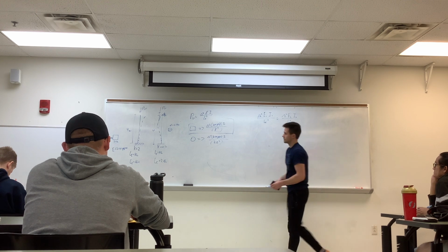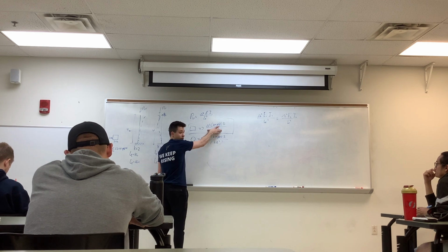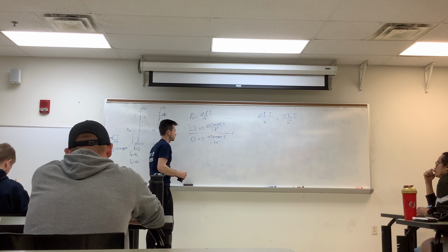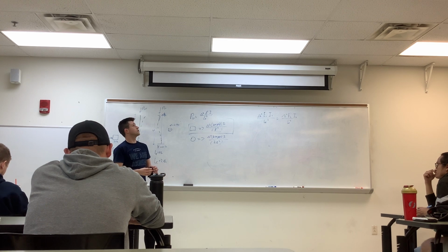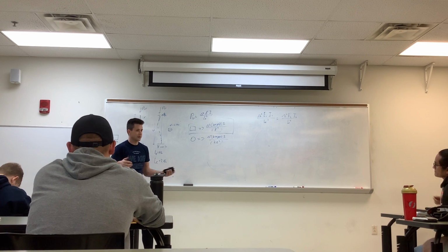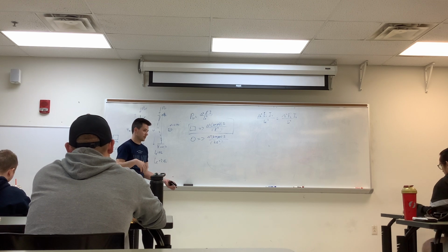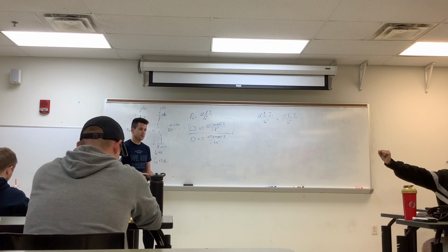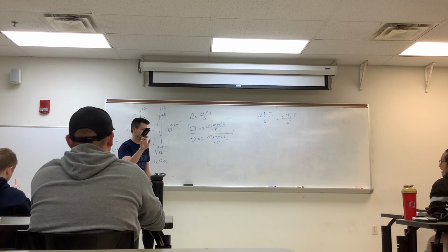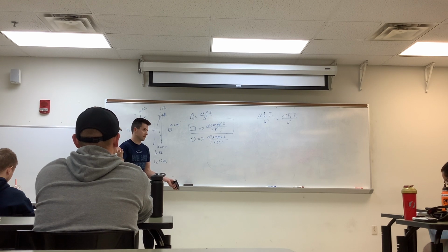But interpreting between these two, this number will actually be significantly greater than this one, because the denominator is so much larger here. So between the two columns, do you want a smaller P? You want a larger P between the two, because the critical load is what the column fails at. Out in the field, you want something that has a higher capacity for loading than something lower, so it won't fail. So it's the other way around: a smaller denominator, the number will be larger.